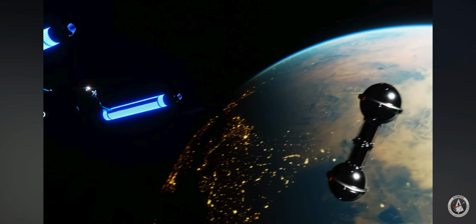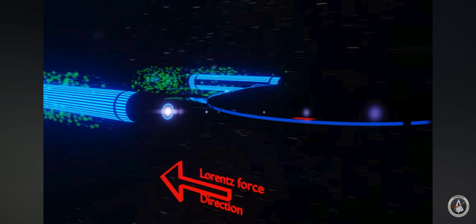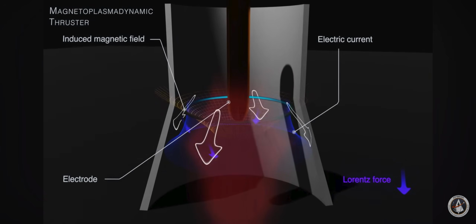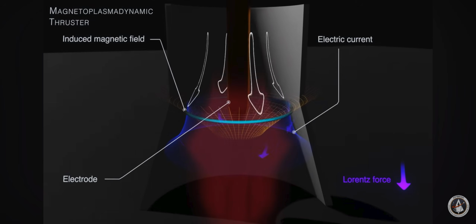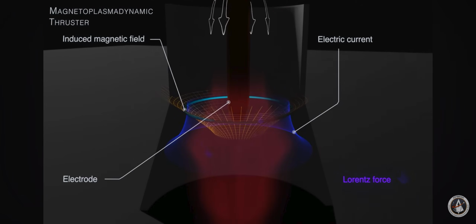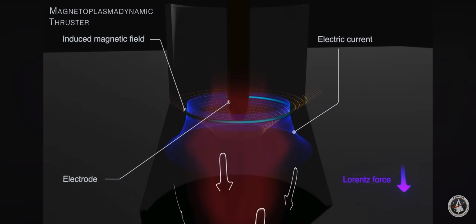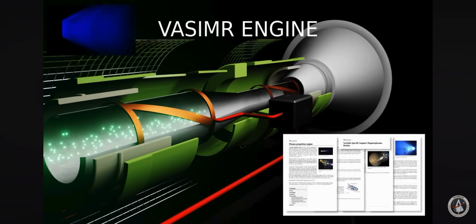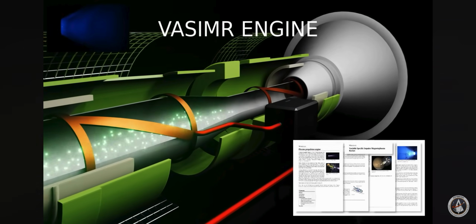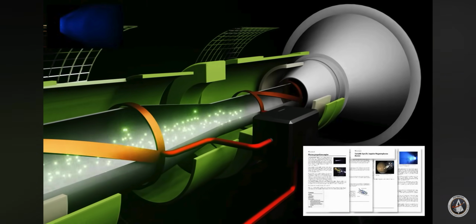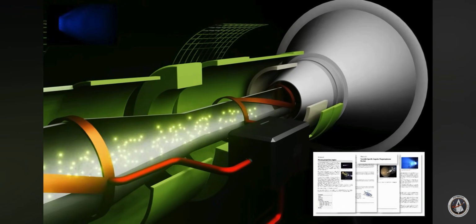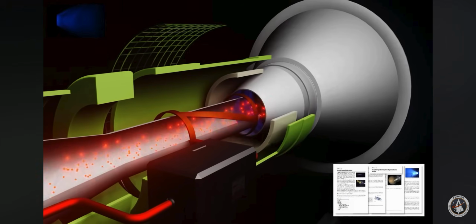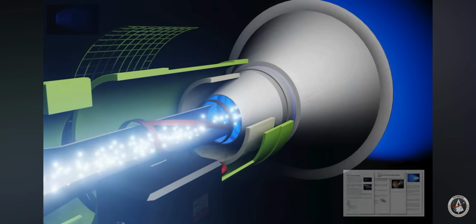MHD propulsion in space. The simplest and easiest form of MHD space propulsion are MHD jet engines, or rather MHD rocket engines. These can utilize the Lorentz force to directly accelerate a cold plasma. Alternatively, radio frequency discharge or microwaves can be used to superheat a gas into a hot plasma state, which is then kept off the walls via magnetic fields, which involves Lorentz forces. The hot plasma is then allowed to escape as with a conventional chemical rocket engine.